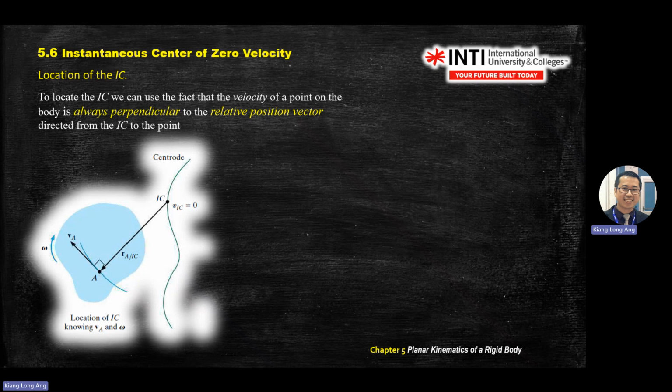So what does it mean? If you want to use this method, the instantaneous center method, you draw your velocity vector, then you use your ruler corner, go to the point and draw one perpendicular distance to a certain reference point. Okay, and then this one becomes your R, and this is the reference point.